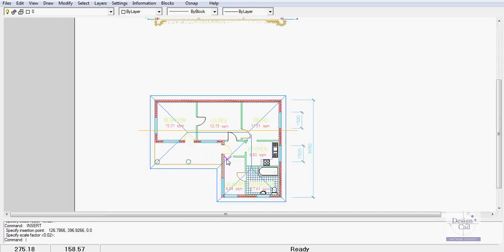We're laying out an A1 size sheet, and this is what we would submit as the finished design. So you design full size in the model space, and you present in the pages palette at the scale that you think is appropriate to convey the meaning. There is, in fact, no reason why you couldn't put that footing design in at, say, a scale of 1 to 10 and put it down in the right-hand corner. But I'll leave you to work through that. The principles behind this are the key issue.